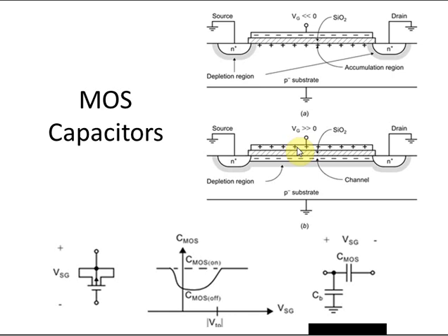And again, if being used in a tuned circuit, like for example an oscillator where you want to have a tuning knob to control the oscillation frequency, the fact that its capacitance varies as a function of voltage can be thought of as a good benefit. On the other hand, it can also be very undesirable if you're applying signal swings across it that cause the capacitance value to vary, and then introduce nonlinearity and distortion. That can be a bad thing. Also, in modern CMOS processes, the gate oxide is so thin that there's a considerable amount of leakage across this capacitor. That can be a problem. The parasitics associated with this capacitor can be large because we're talking about a well to substrate depletion region capacitance. Also, they're imbalanced, so the parasitics are borne mostly by one side of the capacitor.